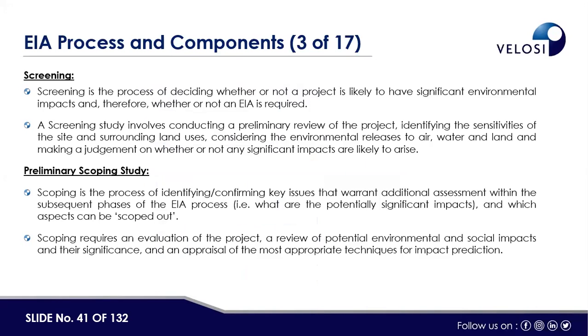So now I will explain what the screening is. Basically the screening is the process of deciding whether or not a project is likely to have significant environmental impacts, or whether EIA is required or not. Basically it is a first step where we have to determine on the basis of available data, on the basis of experience, on the basis of the workshop, whether this project is having any significant environmental impact on the environment. If it is having significant environmental impact, then EIA is required. But at the screening stage, if we come to know that this project is not having significant environmental impact, then EIA is not required. So this is the stage where we will determine whether EIA is required or not.